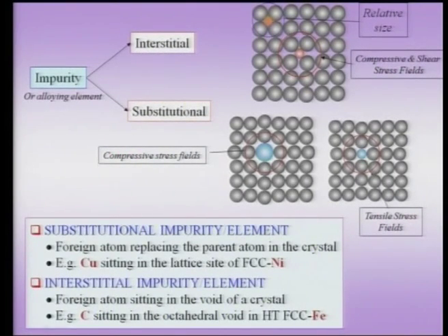previously. For instance, now if I try, and we have seen that when I try to put an interstitial atom, so let me show the interstitial atom sitting at the top here in this picture. So, I have an interstitial atom here. We can see that it is typically larger than the lattice position, and therefore, they cause stress fields and displacement around the position in which they sit.